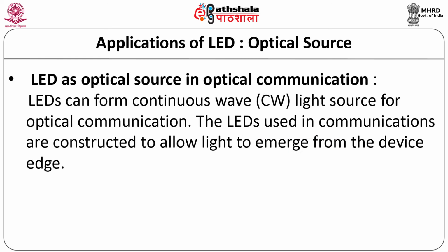Now let us see how LED can be used as an optical source. First let us see how it is used as an optical source in optical communication. One of key components in optical communication is the monochromatic light source. In optical communication, light sources must be compact, monochromatic, stable and long lasting. Therefore, LEDs can form continuous wave light source for optical communication. The LEDs used in communications are constructed to allow light to emerge from the device edge.